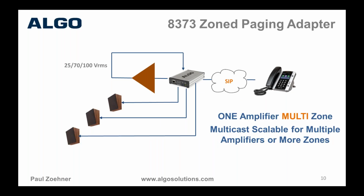And a similar product called the 8373 is a little bit different in that it takes the output of the amplifier, whether that be 25, 70, or 100 volts, brings it back into the adapter, and then internal relays switch that out to up to 3 individual speaker zones. So you can have the zoning here based on the SIP extension that's called.